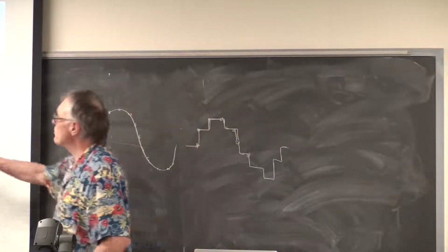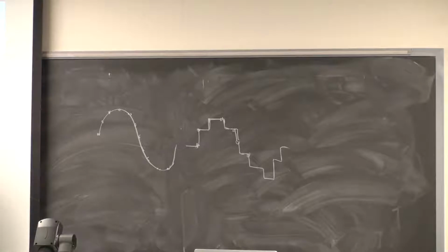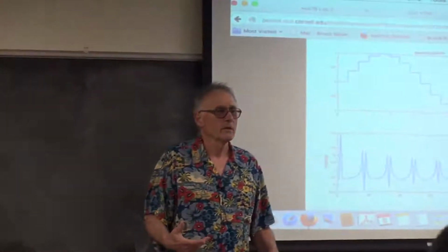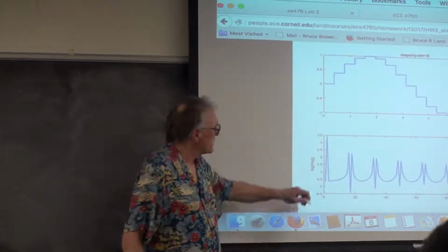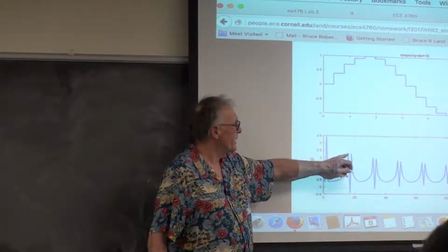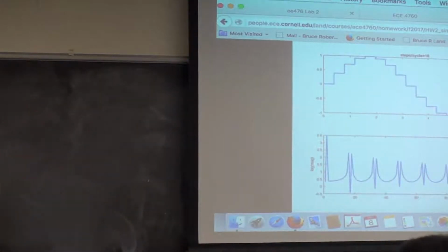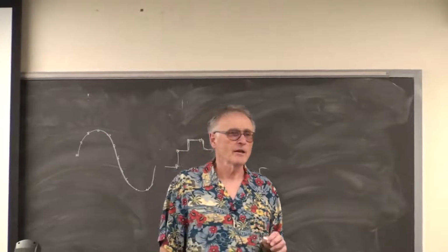You say, oh, that's much more pleasing. If you do the old chi by eye, you squint at that. Yeah, you use your eyelashes as a low-pass filter, right? Then it works. And then you can get a much better feel for a sine wave, and sure enough, the error terms are smaller relative to the peak. By the way, I didn't plot dBs here, I plotted log units, because I like log units better. So each log unit is 20 dBs. So this is a little over 1 log unit down in error term. And by the time you go to 32 samples per cycle, it's way down.